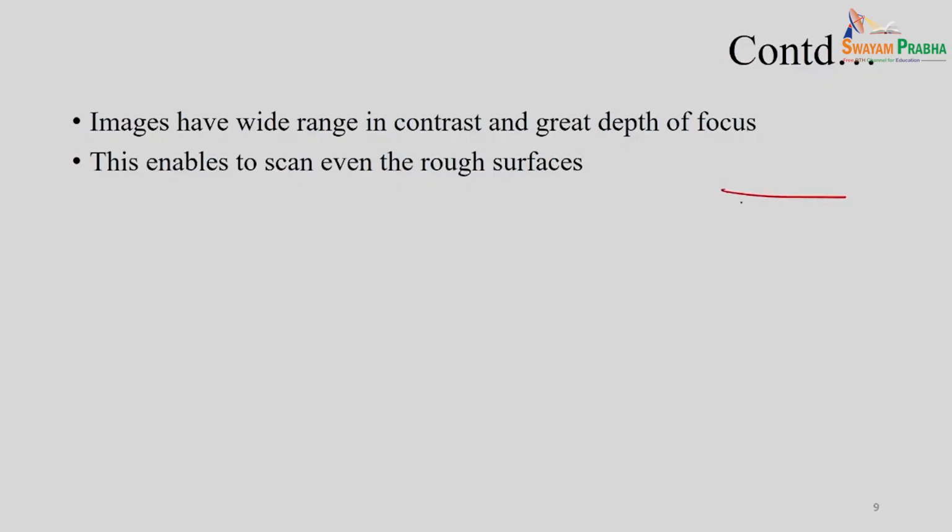but only your substrate or your sample should be stable if it is exposed to the electron beam, and also it should be conductive. So, many times for SEM analysis, let us say this is your sample, we have to sometimes coat some conductive film like silver or gold. Coating is also done before the SEM analysis,